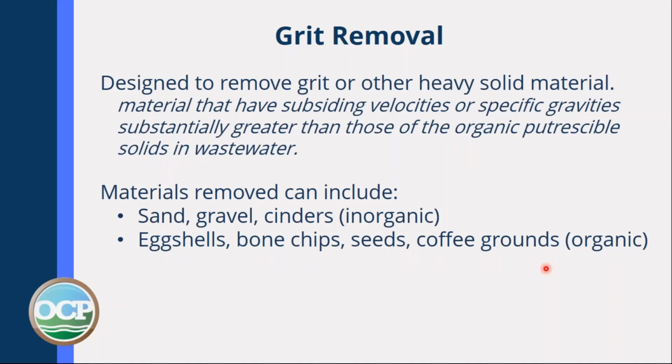Grit removal was the second part of preliminary treatment. So this is taken from the manual. I've put it in italics. I'm not going to read it verbatim. You can do that if you want to. But the idea of grit removal is to remove solid material that is heavier than the water and will sink to the bottom.